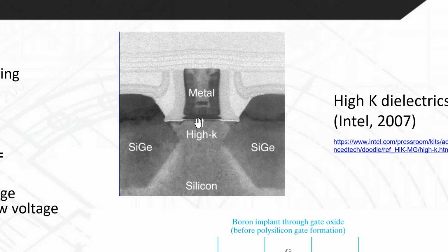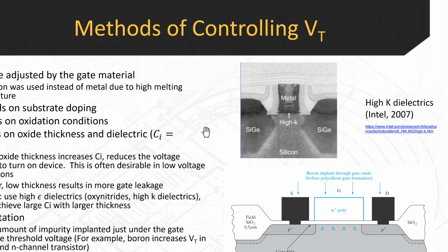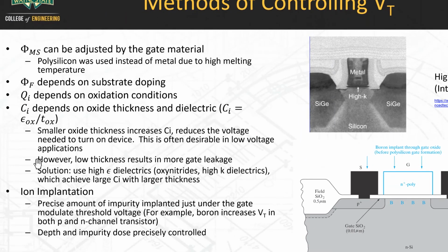All right. So when your gate oxides become that thin, you can actually get tunneling through the gate oxide. So the gate oxide is not acting as an insulator anymore. So you can actually end up getting current going through your gate, from the gate into the source. One of the fundamental properties of a MOSFET is that there's no current that goes into the gate, right? If a current goes into the gate, then your MOSFET's not behaving as it's supposed to in an ideal device. So that gate leakage is one of those issues that can occur. I'll talk more about that in a second.